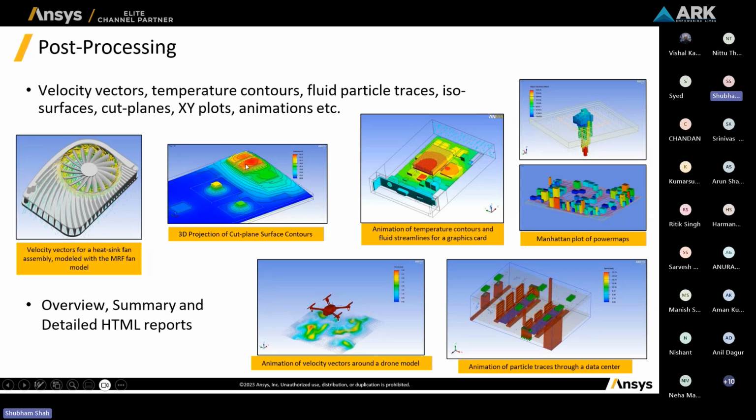Here you can see the red color indicates the higher temperature rise. On the right hand side you can also see a contour legend, where you can compare the temperature. All the temperature ranges are written here. Ideally, at the bottom it will be the minimum range, and at the top it will be the maximum range.